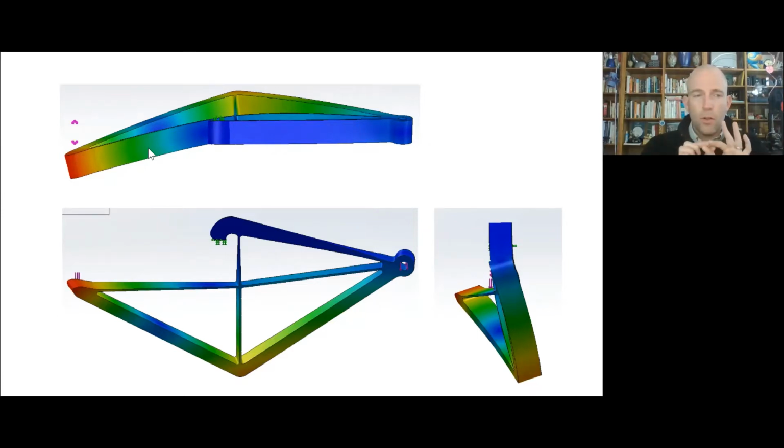They could be square, or they could be tall, or they could be wide. And because this is the dominant buckling mode, it made the most sense here to make them really thin in the vertical direction and really wide into the plane direction, because that gives you the best area moment of inertia for resisting this type of bending. And this is a good way to do this.